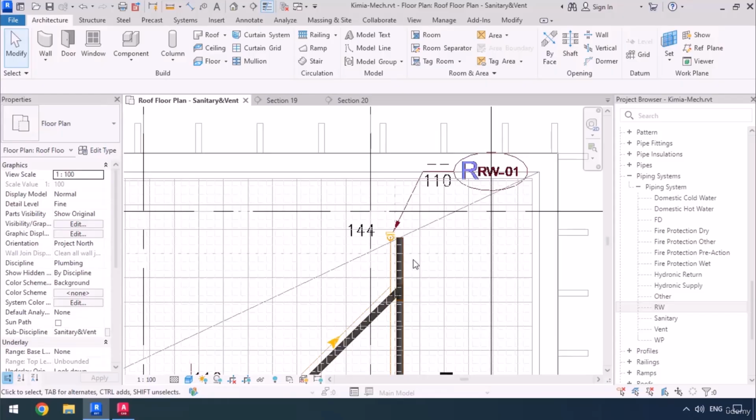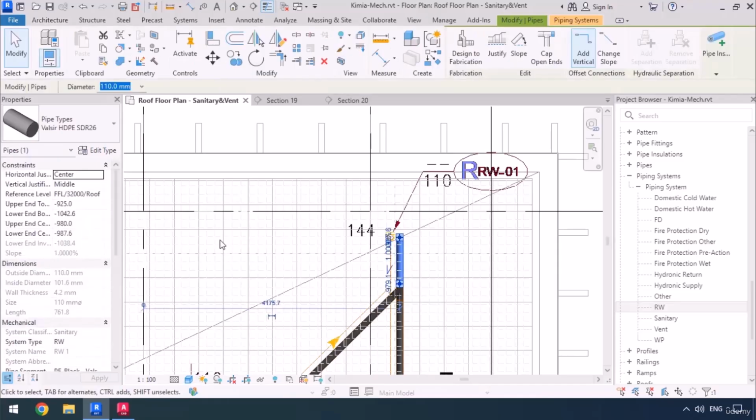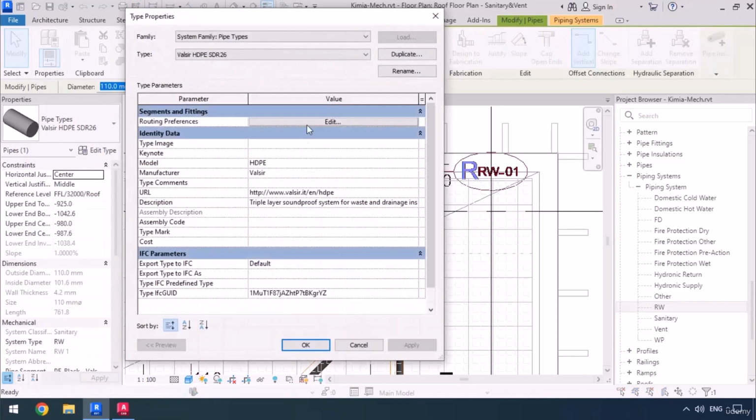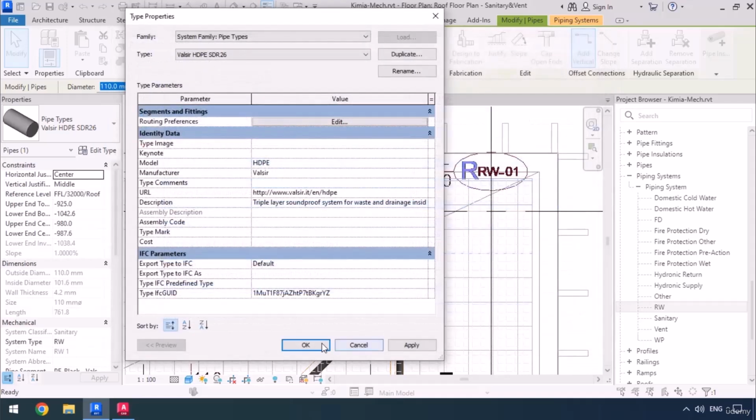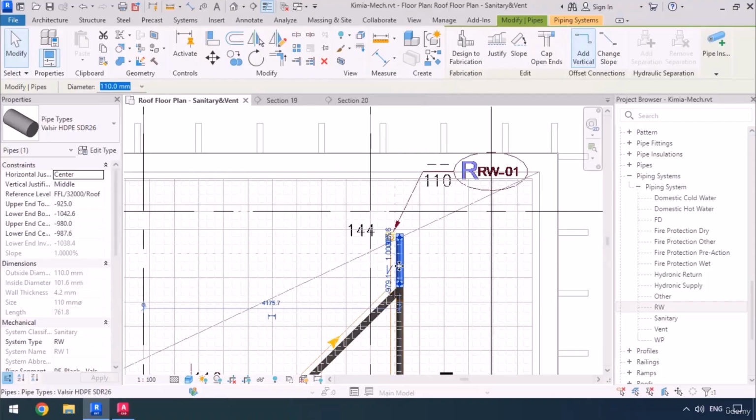And I'm going to be doing the same thing I did in the previous video where we used the two joined 45-degree elbows, which made one family. So first I'm going to select this pipe, then click on Edit Type, and then edit the fittings. So as you can see over here, we've got this double family that has two 45-degree elbows. So I'm going to disable the first one, which is a single elbow, but use this double instead, then click OK and OK. So from here on out, we will be getting two 45-degree elbows which are joined.